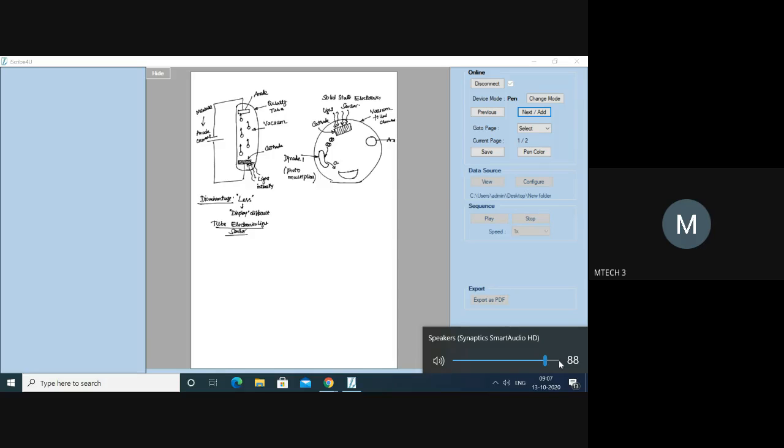Now more electrons are going to be liberated. Then again I want a much larger amount, so I will send them to another dynode. Now what is the dynode doing? The dynode is giving more energy. Now there will be multiplication of the secondary electrons, more secondary electrons are going to occur.